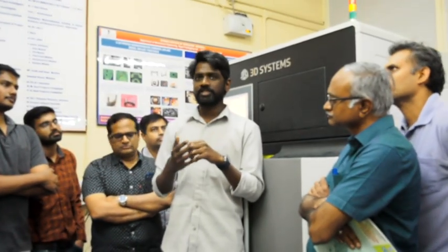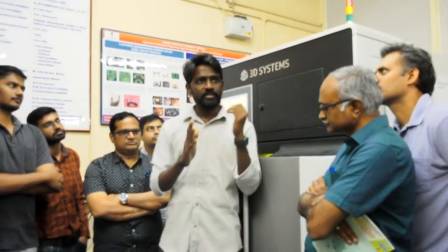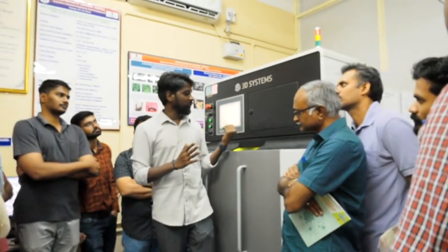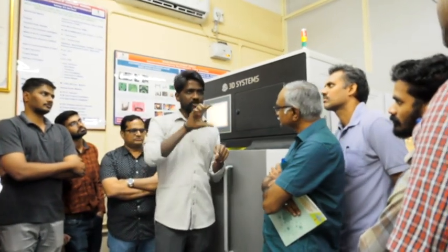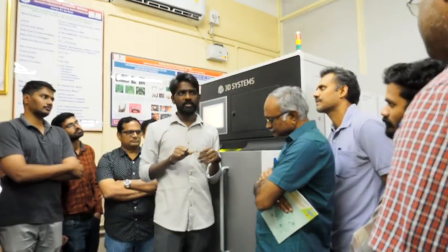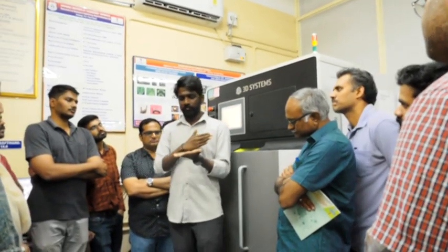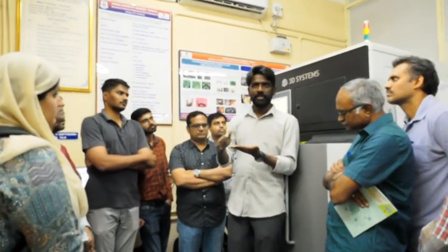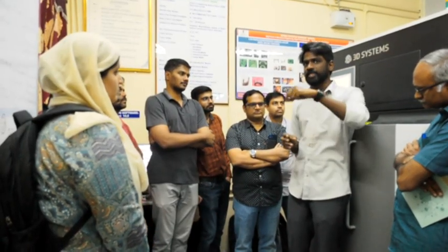I think in the previous session they might have told you about three types of software. In the software we have to design the specified part and send it to the system. It will note down the codes, G-code kind of thing. Then based on those codes, it will follow the sintering process, layer by layer. By stacking the 2D layers, we get the 3D component, right? Before getting the 3D component, the layers have to melt the powder particles.